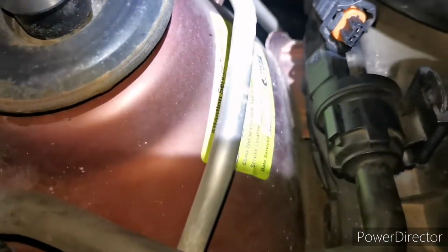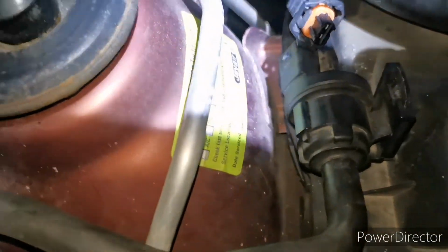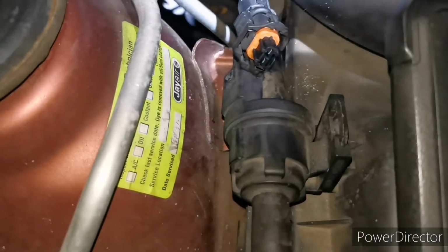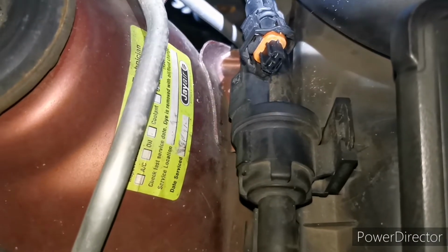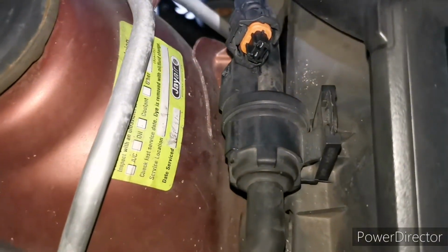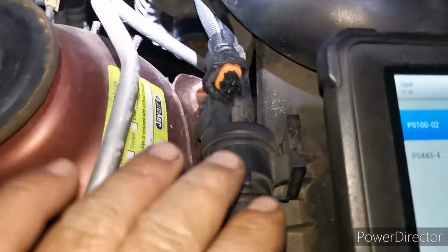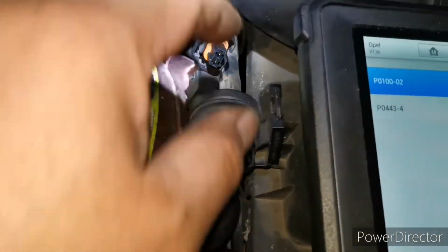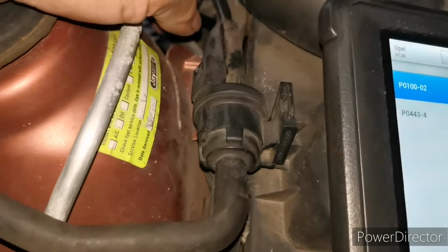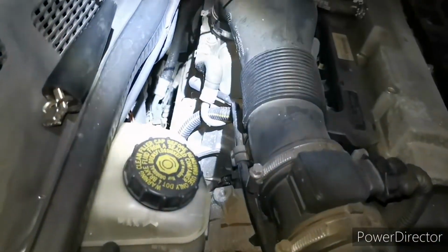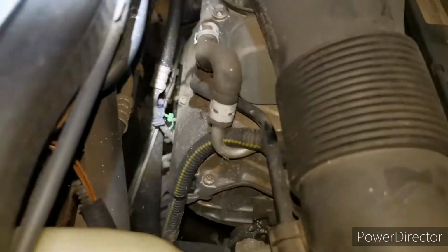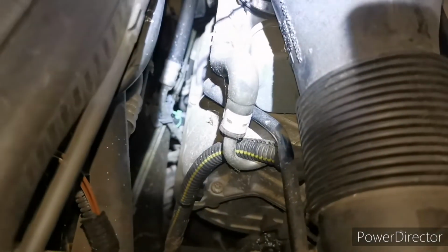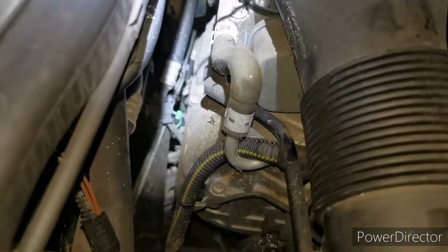Okay, guys, I have found one valve here that is related to evaporative emission control. As far as I know, this valve is our purge valve, because the other end of the hose is going to the carburetor, guys. It goes to the carburetor,